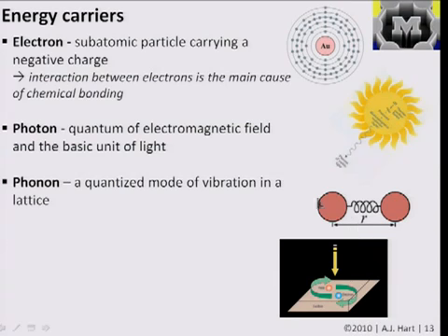And this idea of thinking about bonds or connections between atoms as a simple spring is also one that'll be fundamental to the way we think about mechanical properties. Because when you get down to a scale of a structure of individual atoms, imagine pulling on a nanotube, we can think with some reasonable degree of certainty of that as a collection of springs, and we can use those simple spring models to extract actually a good idea of things like the stiffness and the strength of the material.